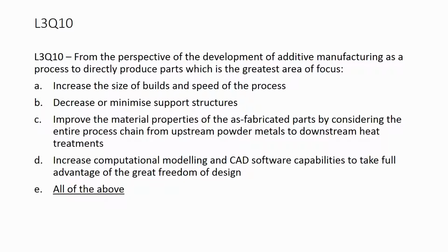But having 4 lasers firing at the same time means you've got more condensate and more evaporate, so the lenses get covered quicker, and there are more problems within the process. That's just an example, but all of these are areas where there's a lot of work being done.